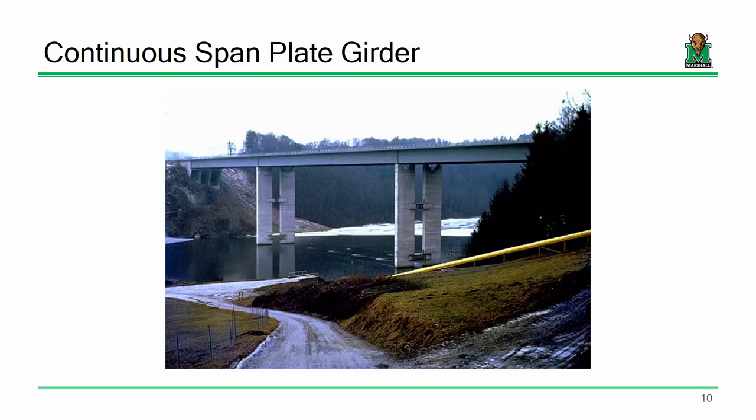Well, because of that, we cannot truck those beams to that site in one single piece. They have to come in pieces, and they have to be spliced together. Where do we locate those splices? That is actually an important point to consider, and something we will discuss throughout this semester. Okay? Now this girder has a uniform depth, or at least for the most part looks like it has a uniform depth.